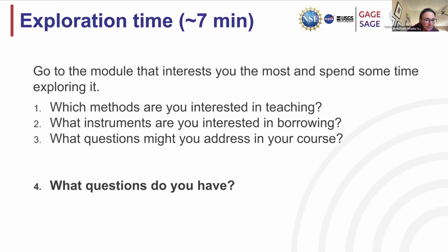Somebody says, we have shallow targets buried at our field research site. This was done way before I got here. Is GPR the best? Well, certainly GPR would let you run over and see if you could find them, since the targets are small. What would you say, Andy? Seismic is really more for where's my bedrock, which is also cool, because lots of places have bedrock within 20 meters.